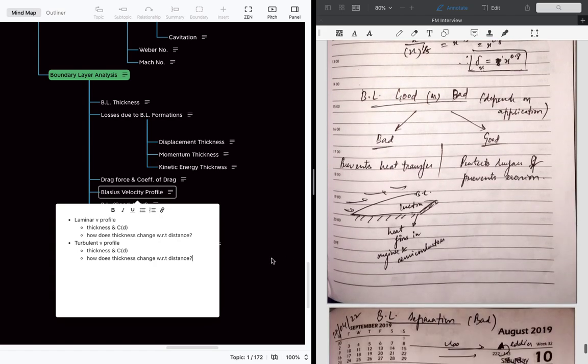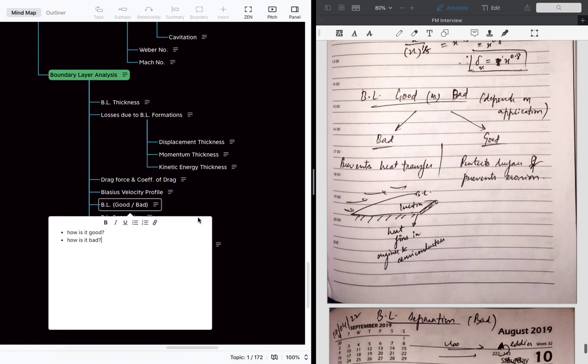So let's know, is the boundary layer good or bad? It basically depends upon the applications. It is bad in the case when we want to transfer heat, because it prevents the heat transfer. For example, an engine or a computer or capacitor which contains wing-like plates to reduce the heat. That means a part is heating here and the plates are attached here, so that the heat can transfer through the plate and dissipate by the convection process. The heat is released outside.